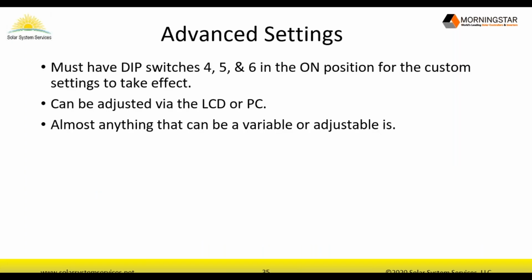Okay, just another note, in order to use the custom settings, you must have DIP switches 4, 5, and 6 in the on position. And again, you can adjust that. You can adjust the standard settings only via the computer or the LCD display.